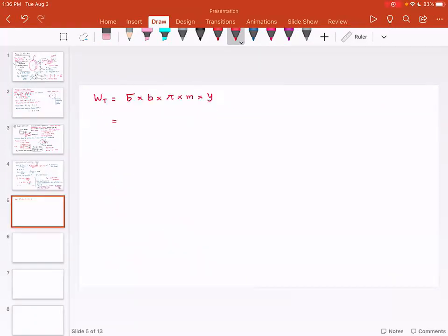So sigma is equal to sigma static multiplied by velocity factor, and that I'm going to assume 140 multiplied by CV, which is 0.26. This is the value for alloy steel.